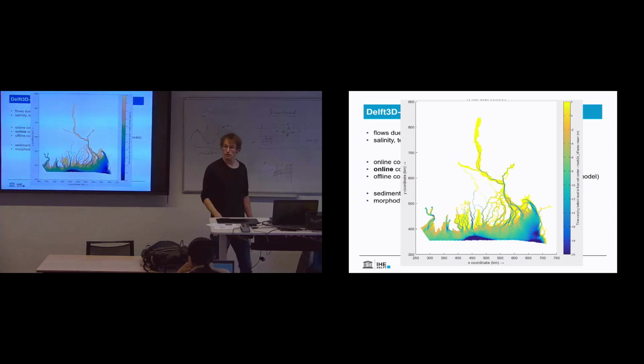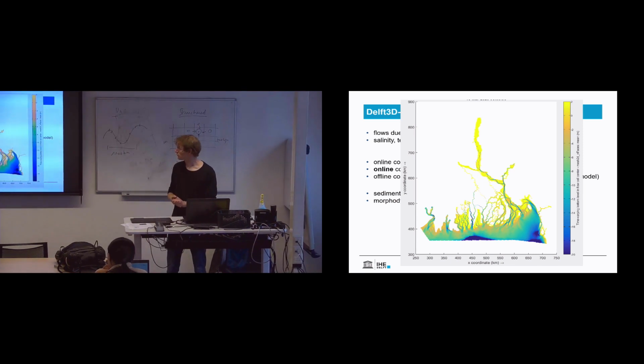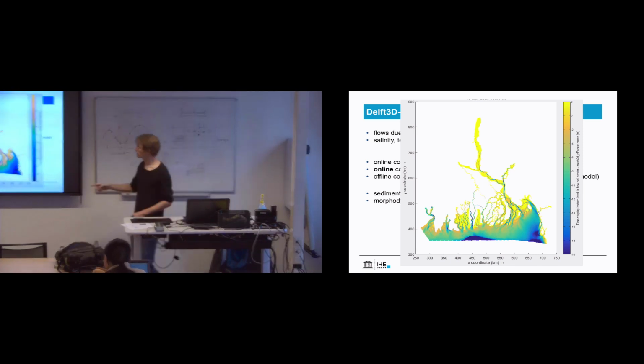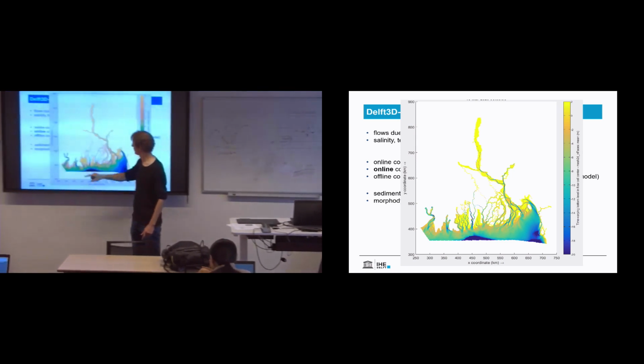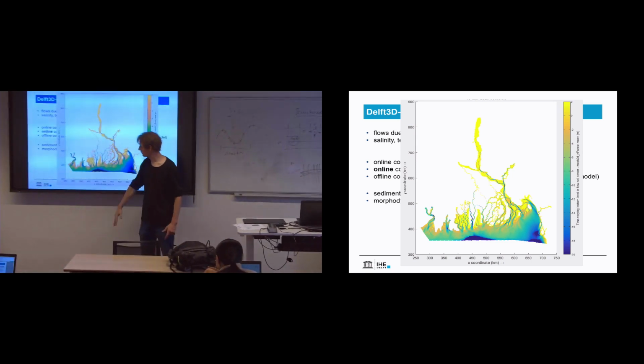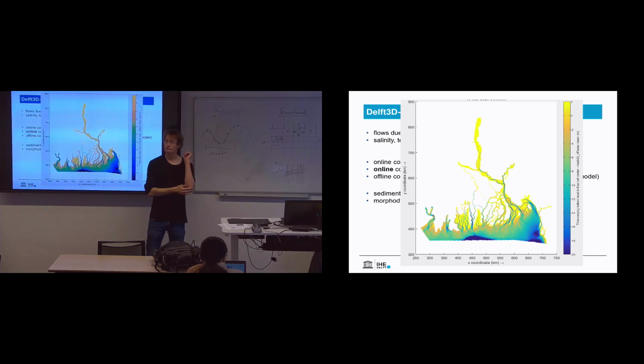Is this modeling for the tidal waves or the river flow? This models flow. So we have discharge boundaries here and here. We have tide boundaries. Well, this domain is larger, so I cut it off for the figure. But we have tidal boundaries on the southern part. We have a wave model that's on top of this, and we also have wind. So we have wind, waves, discharges, tides, sediment transport, and morphology as well, covering like half Bangladesh. What about the sediment formula in flexible mesh?